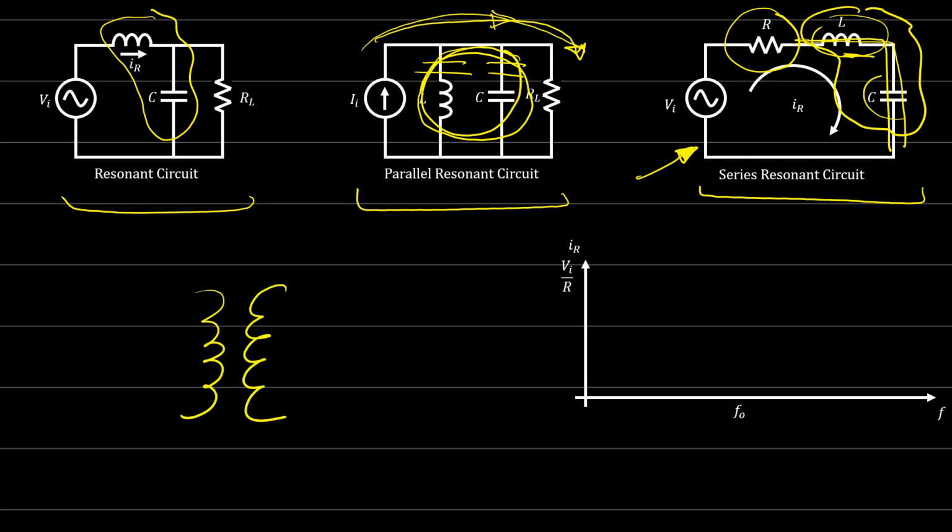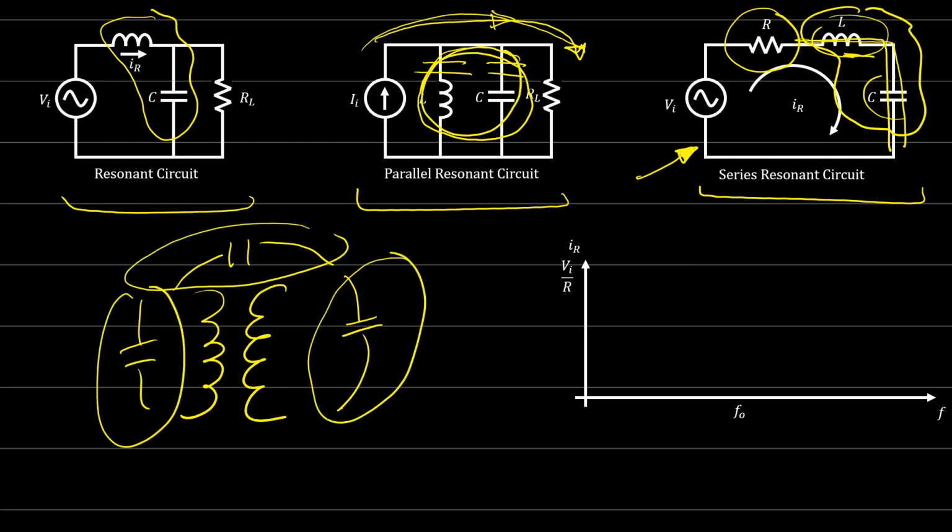If you look at the transformers, for example, if you remember, we said we have loads of parasitic elements in the transformer, and these parasitic elements like capacitors, inductors, which are not actual passive elements, when we increase the frequency, the value of these capacitors, inductors can increase, right? So what is the best way to cancel these elements? If we have a capacitor here and manage to add an additional inductor to cancel the effect of this capacitor, we can extract the maximum power. Okay, so this is one of the advantages.